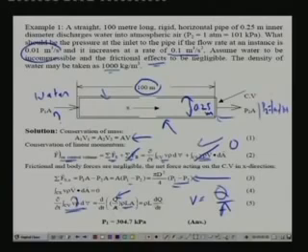So ultimately you have rho L dQ by dt, and in the problem it is given that dQ by dt is 0.1 meter cube per second, rho is given as 100 kg per meter cube, and length is 1 meter. If you substitute these values here and then use equations 1 to 4, you get the answer P1 is equal to 304.7 kilopascal absolute. That means the pressure here should be 304.7 kilopascal, so that the flow can take place.